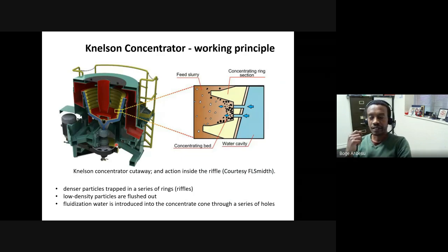As I said, inside that separator is a bowl that is rotated at a very high rotation speed, and the bowl itself has some grooves inside it. Hopefully you can see those grooves from my picture there. There are lots of lines or grooves inside it. That's actually where we trap the particles. Now feed comes from the top, feed falls here from the top, and in this case you have feed mixed with water, or particles mixed with water.